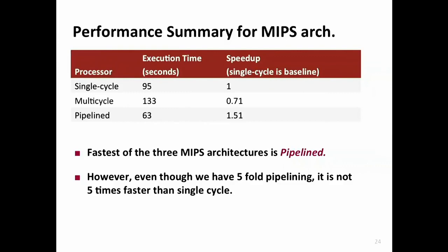But clearly we've pipelined, we have 5 pipeline stages, but we didn't get 5x the performance. Our pipeline efficiency is terrible actually, right? It's only 1.5. Well, you can think about why that is the case, right? Basically, this is always true. It's very difficult to get 5x improvement with pipelining. But this is also on the lower side, in my opinion, so you really need to rethink the design of the pipeline a little bit if you get numbers like this when you design a processor.